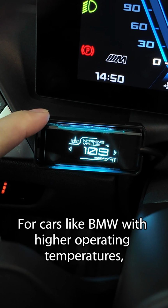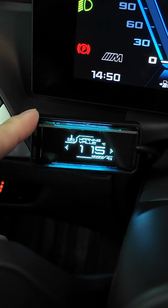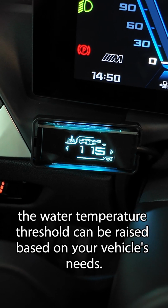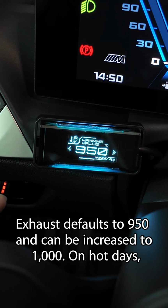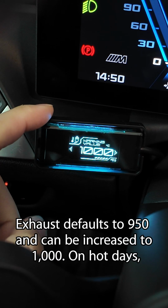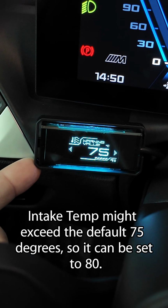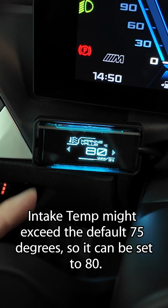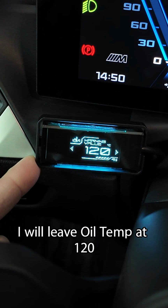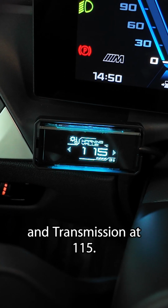For cars like BMW with higher operating temperatures, the water temperature threshold can be raised based on your vehicle's needs. Exhaust defaults to 950 and can be increased to 1000 on hot days. Intake temp might exceed the default 75 degrees, so it can be set to 80. I will leave oil temp at 120 and transmission at 115.